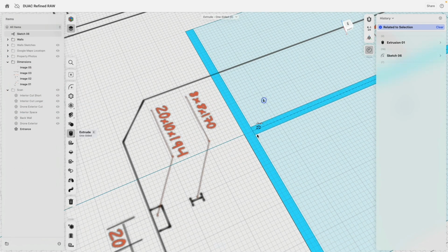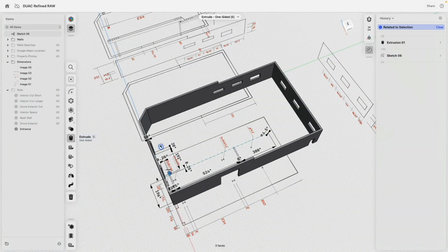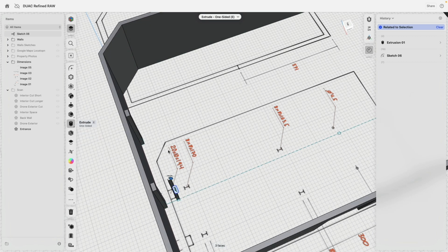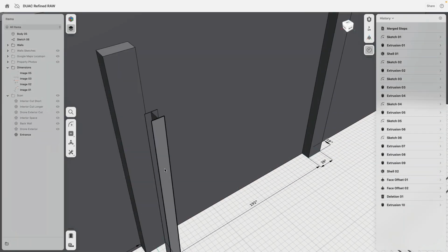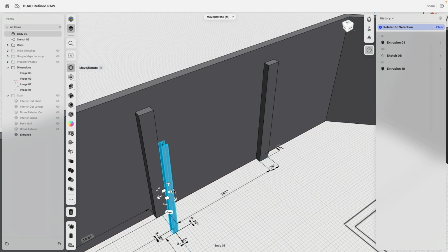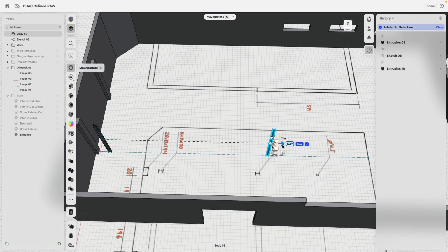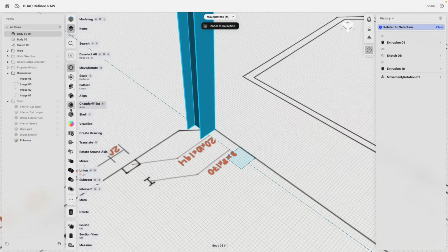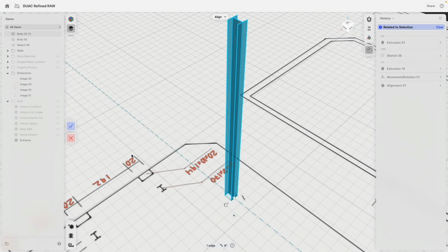So with this way, as you can see now, I have an H, and that is now what I can very easily extrude 170. There, 170. Okay. The question now is, how do we do the other one? That's actually pretty easy. We have one masterpiece. I can make a copy, move this over, and then align this edge to that edge of the sketch.